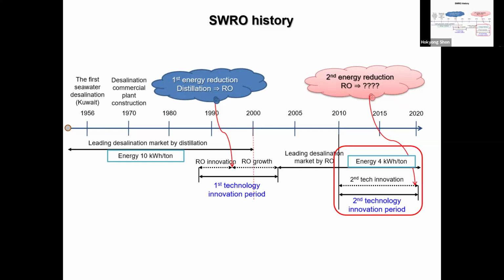And we also had some breakthroughs, with new membranes continuously developed. Then advanced fabrication processes and material development continuously improved the overall performance of reverse osmosis. That's the reason why now seawater desalination uses 4 kilowatt hour per cubic meter of seawater.